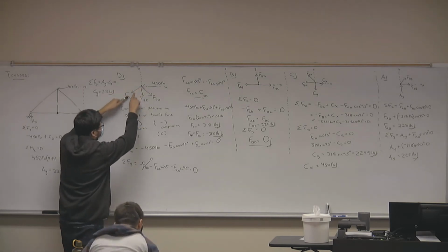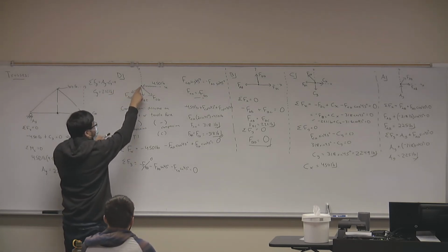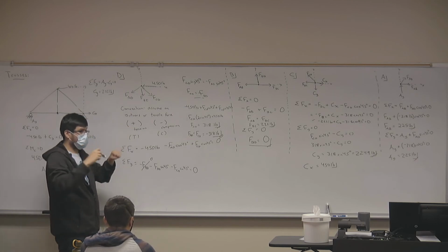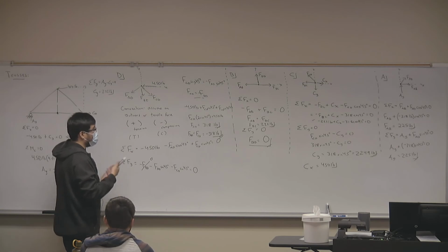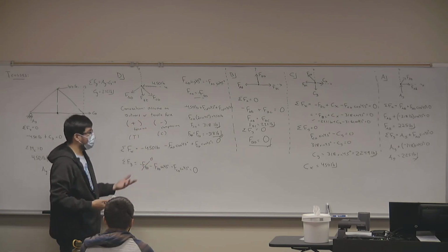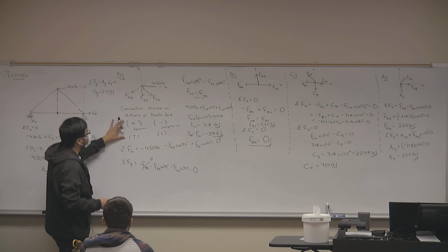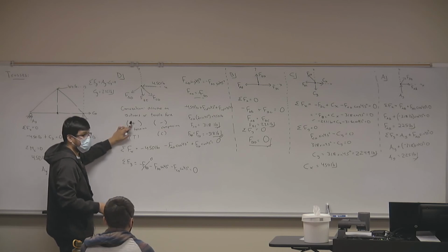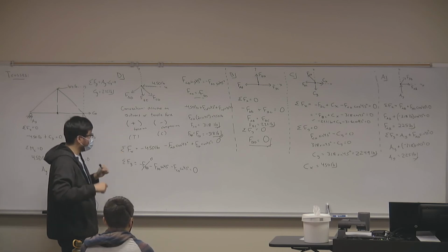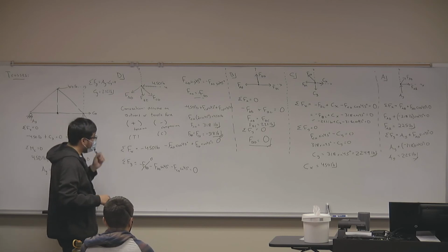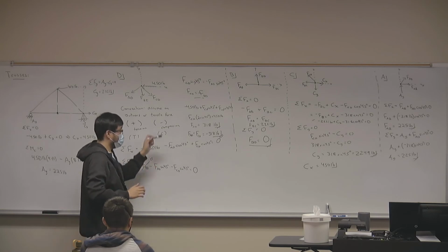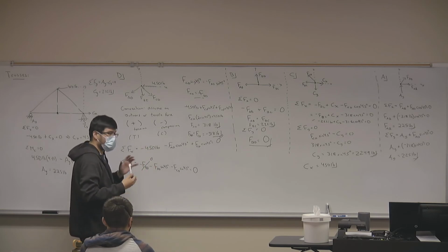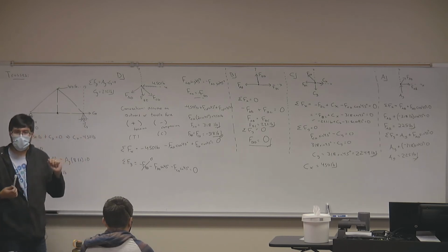If I'm pulling out of it, the force is out, then I'm exerting a tensile force. So that's tension. Pull is tension. From convention, because we don't want to confuse ourselves with all these different forces acting in different directions, we say that a force is positive if it's in tension. So if you're pulling, it's a positive force. And we say that a force is negative if it's in compression. So if you're pushing, it's a negative force. And that's just for convention. That's just to help us not get lost within all these equations.